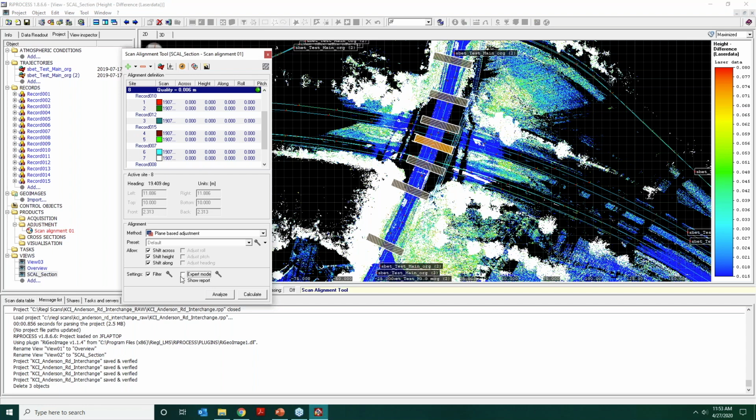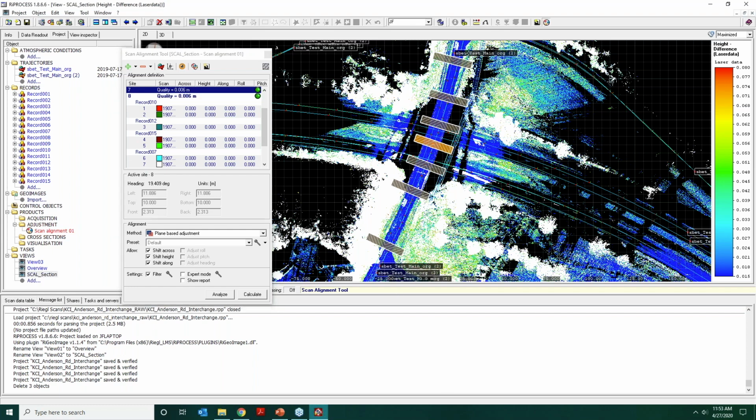So excuse me, I need to back up one quick tick here. So the first thing I did after I created all these sites was I hit the analyze button and analyzed them all. All right, because in order for you to know how changes affect the previous or the post site, you have to analyze the data because that's how it takes in the calculations. And then the ones in the middle here, so I set this one here, which is site 7, and this one here, which is site 1, as my fixed points where I want the data to stop making any adjustments beyond those 2 barriers.